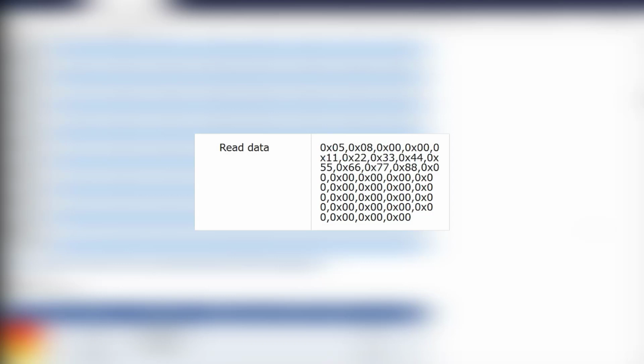And just to clarify, the web interface is going to show all 28 bytes of read data even if you're working with fewer bytes. For example, your tag may actually have data in all 28 bytes. But if you say only read the first 8 bytes, you'll see only the data in those first 8 bytes. The remaining bytes will just display placeholders shown as 00, seen here. It's only going to retrieve or write what you ask it to.